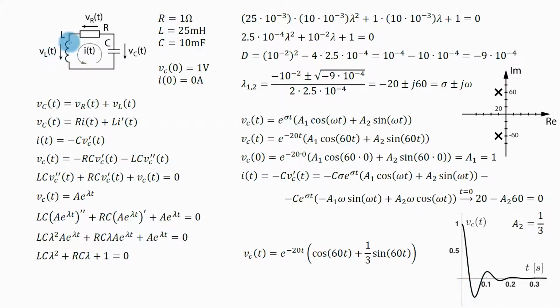At some moment, the energy stored in the magnetic field of this inductor will dissipate and this capacitor will no longer be charged. That is this point. The voltage on the capacitor is no longer increasing to negative values. So now we have the capacitor charged to some negative voltage, and basically the entire process repeats itself.